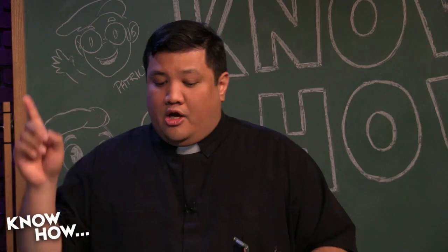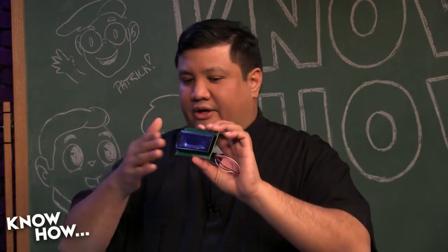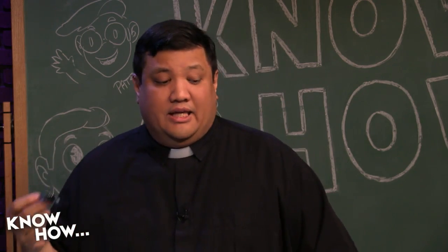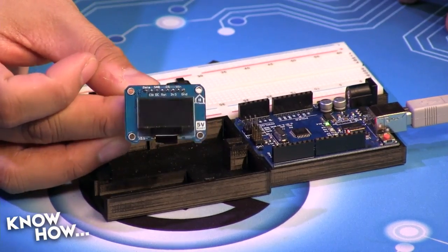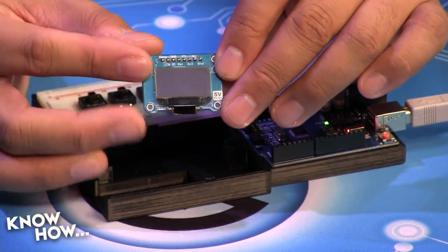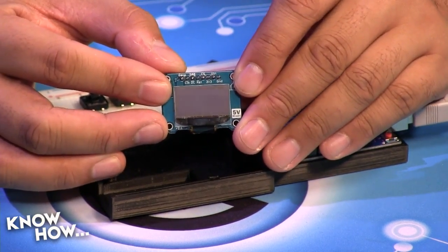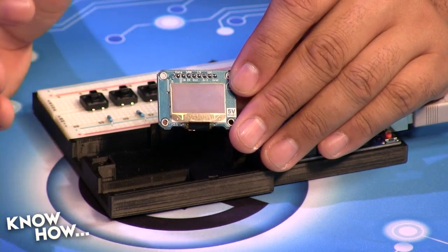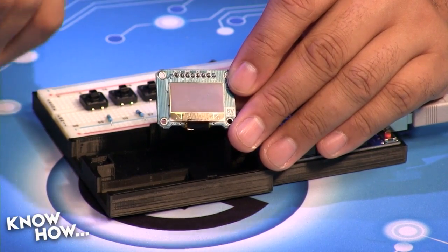Same thing. Precisely. OLEDs work differently. With an LCD, I have the crystal, and then I have something that creates light behind the crystal so that I can actually see something off that crystal. OLEDs aren't that. There is no backlight because the screen itself is the light. OLED stands for Organic Light Emitting Diode. If you go to the side shot here, Kara, this tiny little screen looks like an LCD, but there is no backlight. The screen itself is the light. So when it creates a pattern, it's not just occluding light or tinging light, it's actually emitting the light.